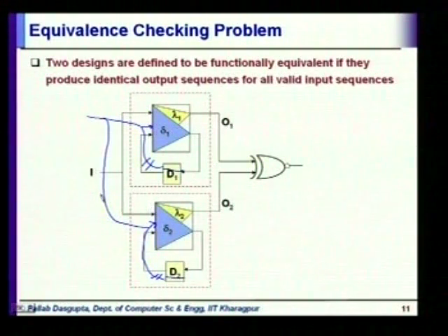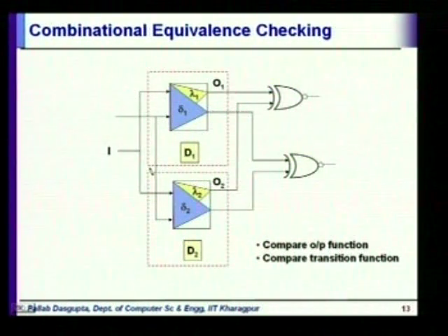All right. So, with that transformation we get something like this. These are the register outputs; they are no longer coming from the flops, they are feeding into the combinational logic. Let us call this S, because it used to represent the state.